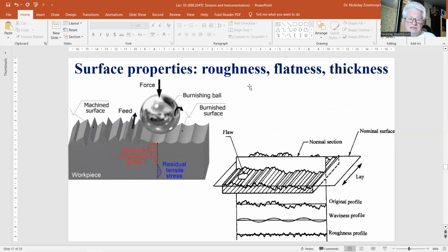Triangulation is applied in a multitude of applications where an accurate contact-free distance measurement is required. Very high resolution is needed in applications like roughness measurement and profile measurements too. In such applications, one-dimensional laser triangulation is combined with a two-dimensional scanning mechanism. A triangulation system is described that performs the simultaneous measurement of surface roughness and surface height. It means displacement in the normal direction.